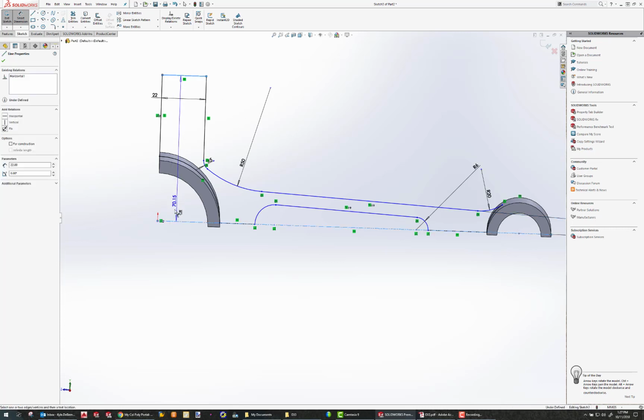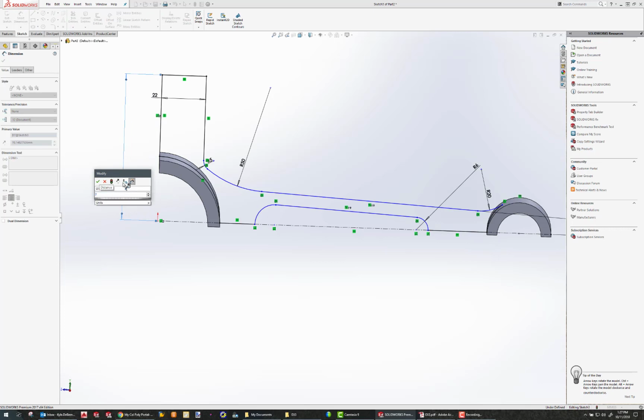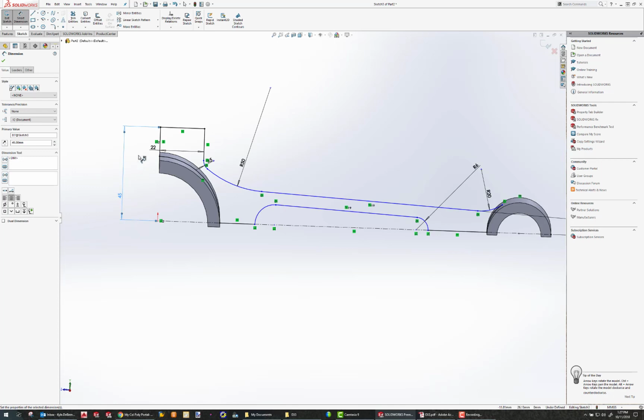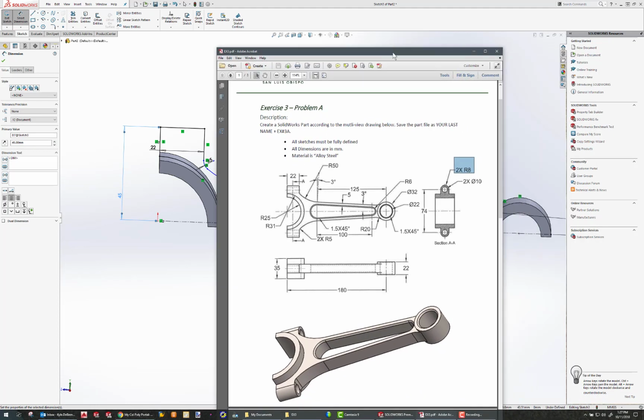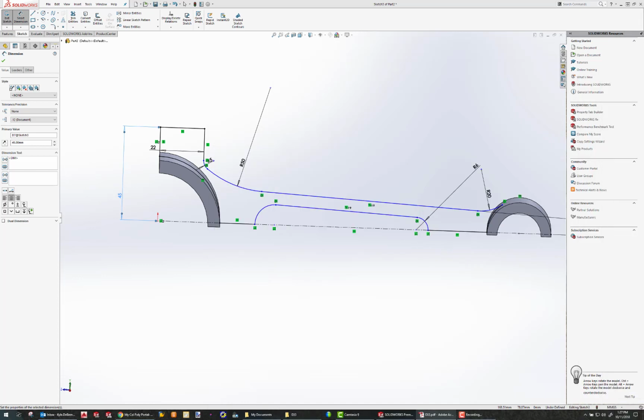The overall height of this is, let's say 74 divided by 2 plus 8, because that's a thickness. 8 is the radius, 74 divided by 2. So 74 is my center to center distance, and then plus the radius is 8. So I'm basically modeling, I'm going to extrude this so it's going to be a sharp edge, and then I can round the corner later.